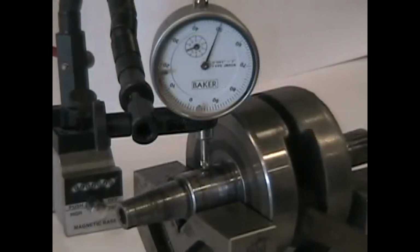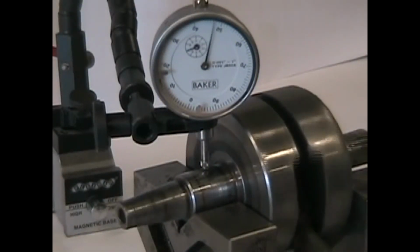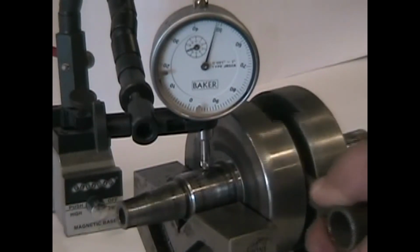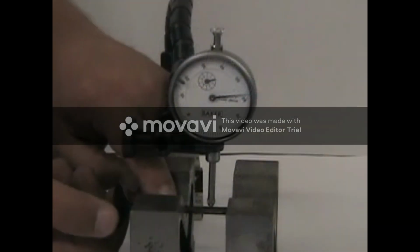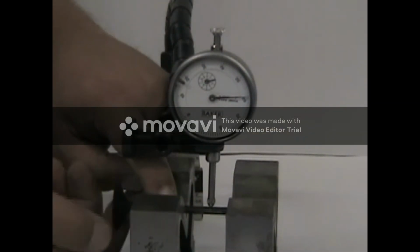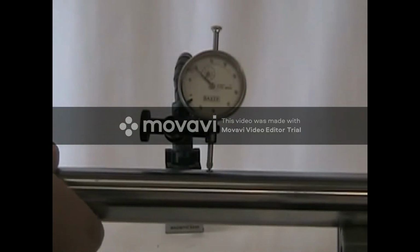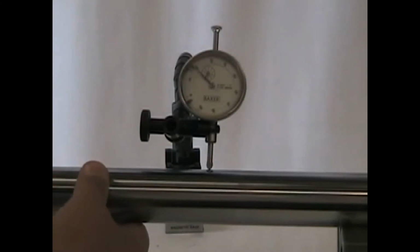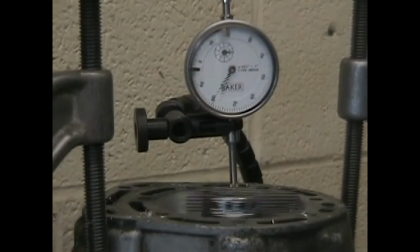The dial indicator is a useful tool that can be used to measure runout, piston position, bent shafts, valves, or for brake rotor warpage. It is a simple and easy to use precision measuring tool that all mechanics must master. Some dial indicators can measure smaller than 1/1000th of an inch. Most mechanics will not require this kind of accuracy, so this lesson will focus on how to use a dial indicator that can read to within 1/1000th of an inch.